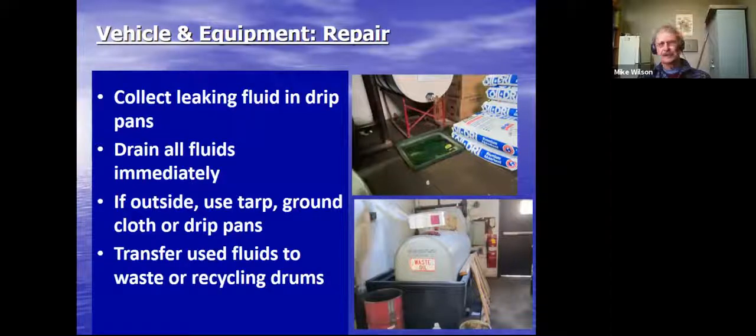So collect your leaking fluid into drip pans. Drain all your fluids immediately on stored equipment if you can. And if outside, use a tarp, ground cloth, or drip pans to collect it. Transfer used fluids to a waste or recycling drum once you get it collected.